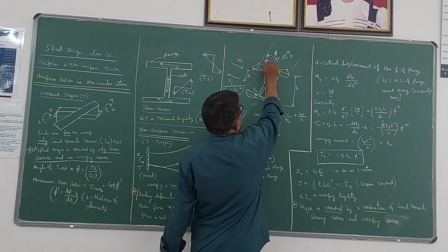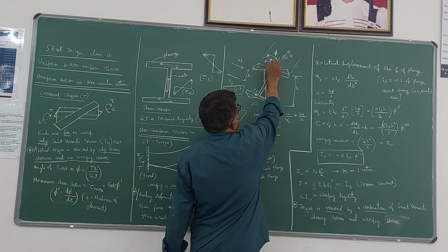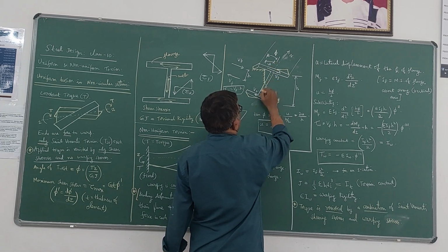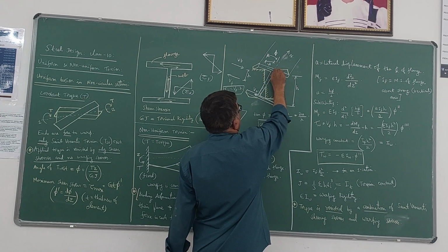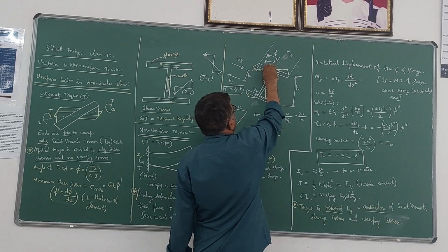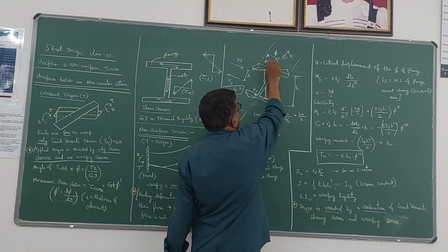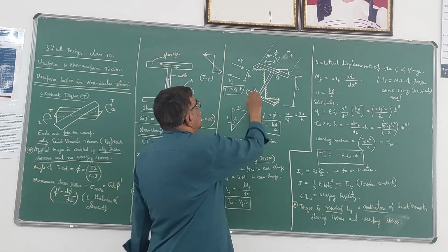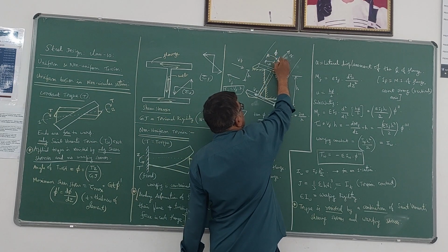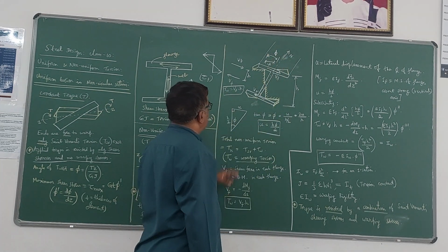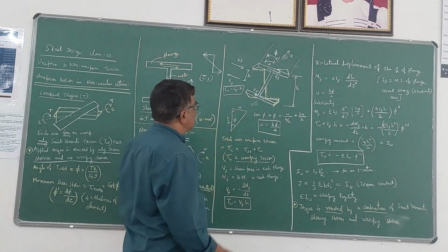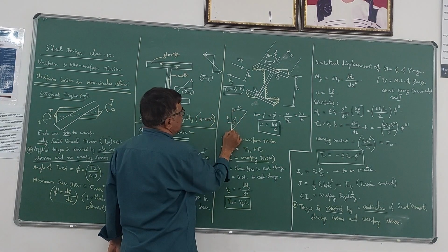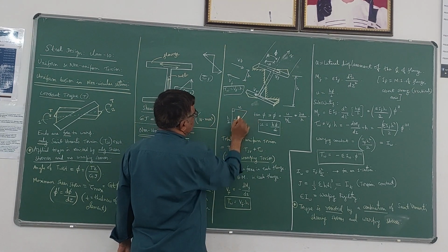And here you can see there will be some lateral displacement of the center line of the web, or of this flange, the center point is displaced here. So that lateral displacement I can call u, and this angle is phi. So if you observe that geometrical relationship, this is h by 2, this is u and this is phi.